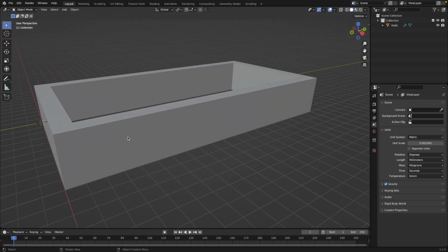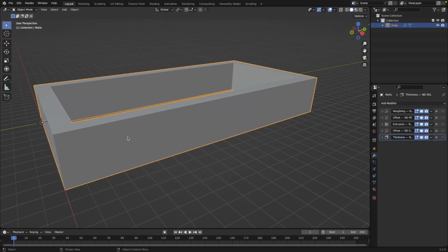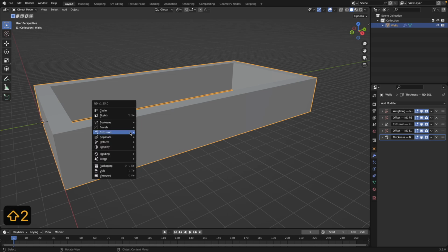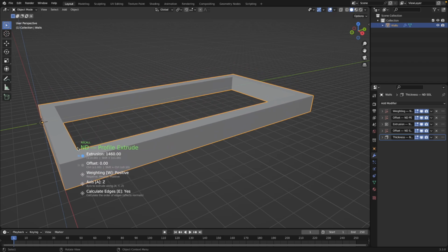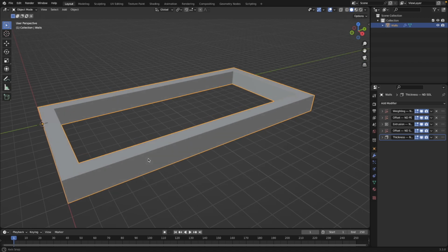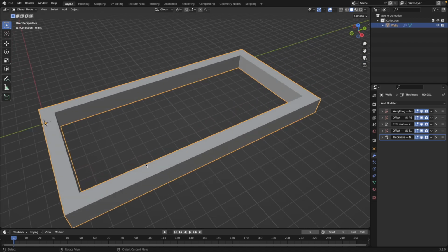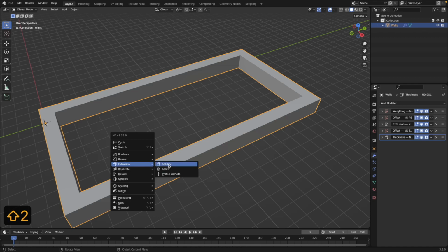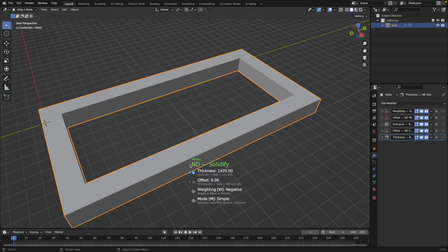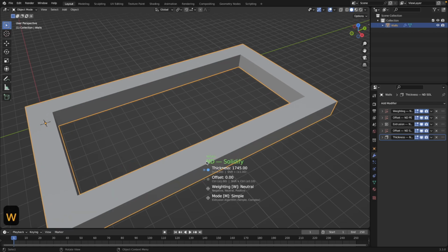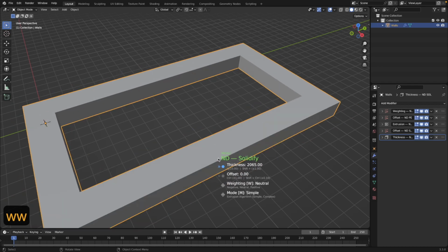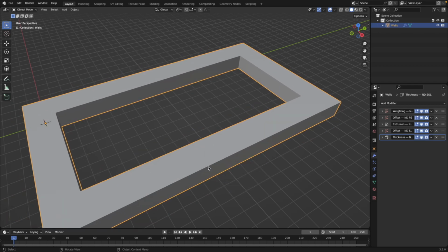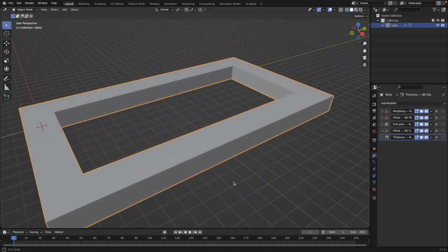But before we do that, I want to make this frame a little bit shorter. So I'm going to change the profile extrude that we did, and I'm going to drag this down just so it's not quite so tall. I want to make a flatter looking vent with these angled slats in it. And while we're here, let's make the outside frame also just a little bit thicker, beefier, like so. You know what? Let's weight it outside of the, yeah, this seems better. That way we've got more room inside of it to work on. So something like this will be the shape of our outer frame.